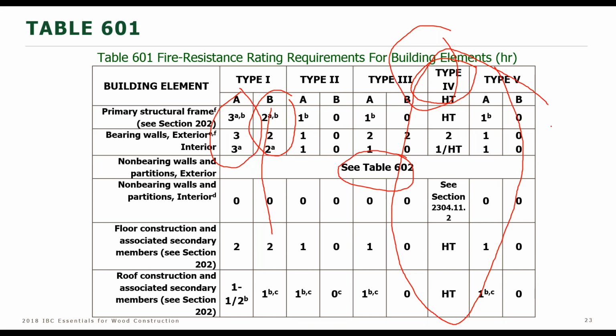Yeah, and again, some helpful comments coming in here from some other AWC staff members. Just to remind folks that Type 4C does not require gypsum covering. That's a fully exposed heavy timber application, even though it requires the fire rating that you mentioned. Yeah, that's a good point. 4C will require 2-hour ratings throughout for exposed timber, but no non-combustible protection. So as you might guess, Type 4C will not be permitted to go any higher above grade than current Type 4 HT as a result.